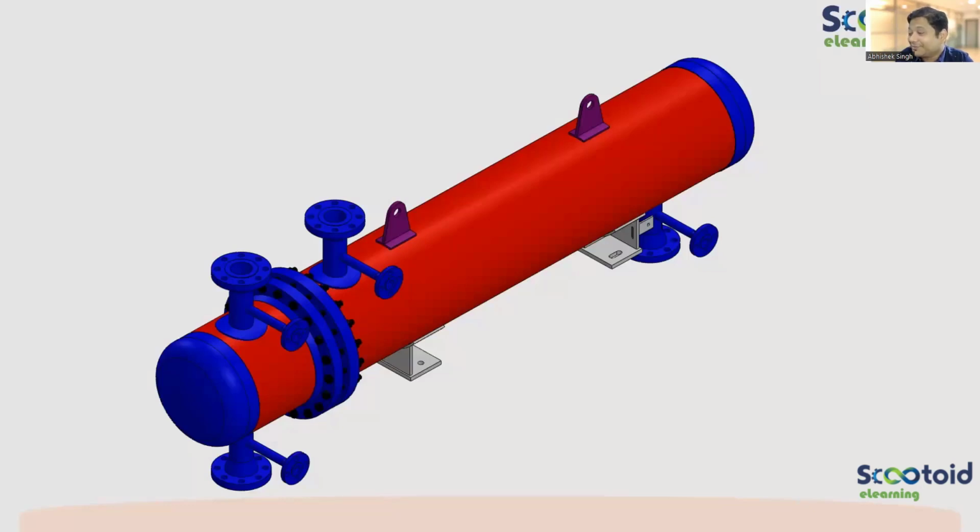First of all, only one tube sheet. Absolutely right. In a fixed tube sheet exchanger, you will be able to see two tube sheets, right? So one is gone, it cannot be fixed. What about floating? How, by just looking at it, can I say it's not floating? It also requires two tube sheets.